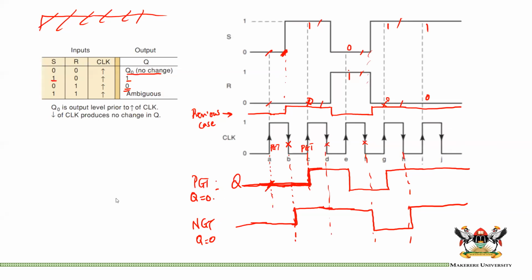Sebakoni, Akram, is the clock providing the setup time? Yeah, the setup time comes from the clock for sure. No, it doesn't come from the clock actually. The clock is the clock, but the setup time and hold times apply to the control inputs. So if you know that my clock is going to come in the next 20 nanoseconds, and you know that the requirement for setup time is 10 nanoseconds, you should do it within that time. You could say if my clock is 20 nanoseconds away, and my requirement on setup time is 10 nanoseconds, I should make sure that in the next 10 nanoseconds, I have changed my inputs.